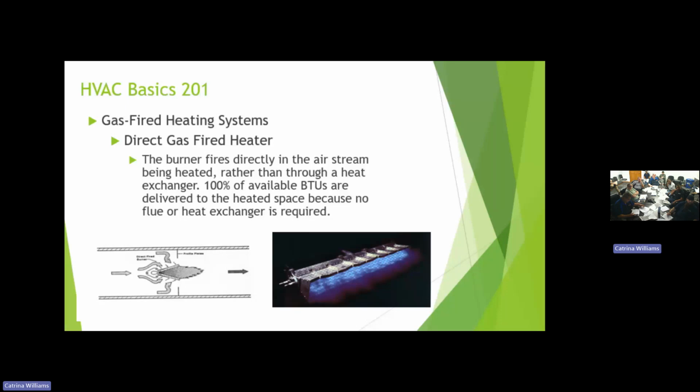It gets a little bit bigger in the middle, the holes increase to, let's say, 1/4 inch, 3/8 of an inch. You get to the very end, it's well over a half, because more flame gets combustion air past the profile plate through the air itself.